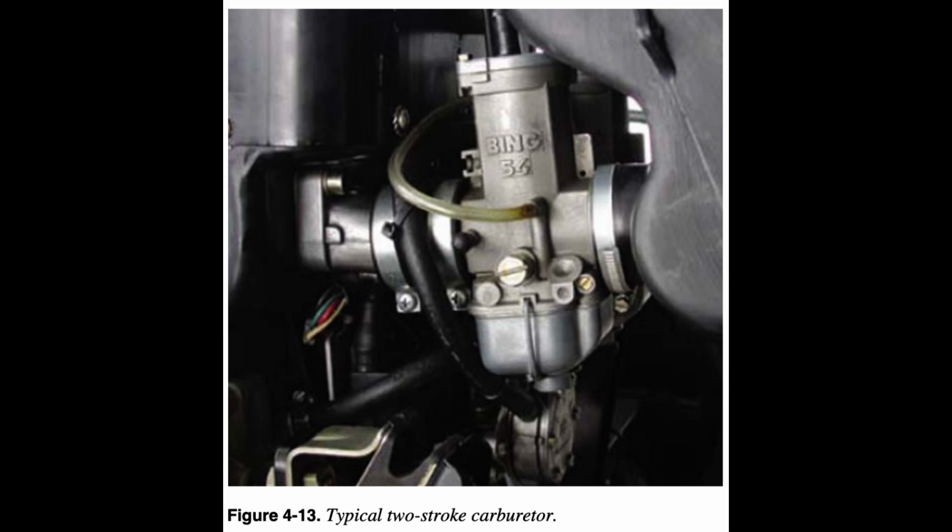Carburetors are normally set at sea level pressure with the jets and settings determined by the manufacturer. Figure 4.13. However, as altitude increases, the density of air entering the carburetor decreases, while the density of the fuel remains the same. This creates a progressively richer mixture, same fuel but less air, which can result in engine roughness and an appreciable loss of power.